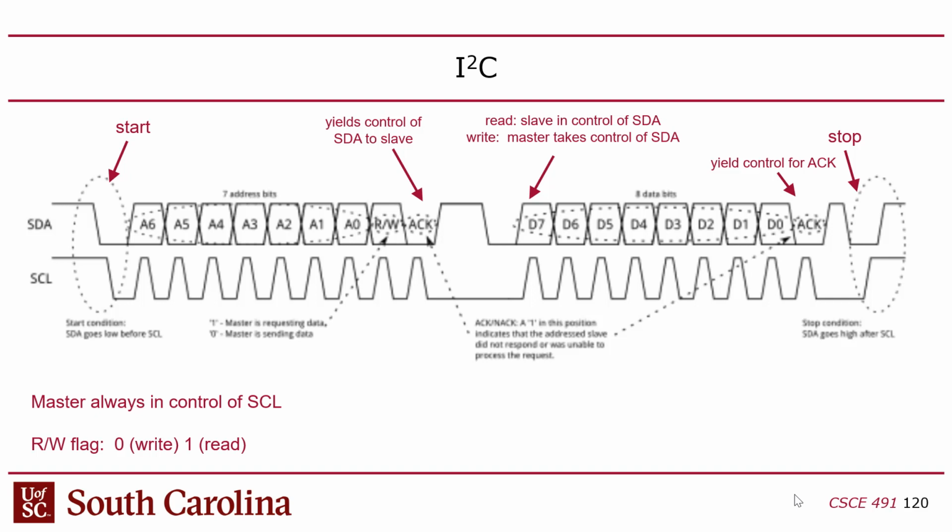The only time that's allowed to happen is a way to indicate to the bus that something significant is happening. I am changing the data while the clock is high. That means it's a start signal, right? Likewise, the stop signal is when the clock goes high basically to its idle state, and then the data goes high to its idle state. That's the stop signal, right?